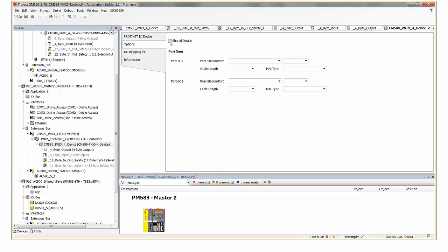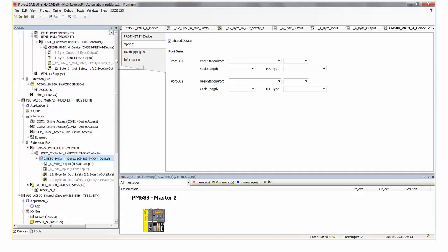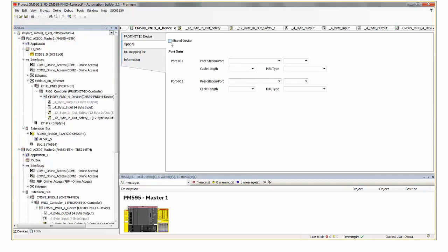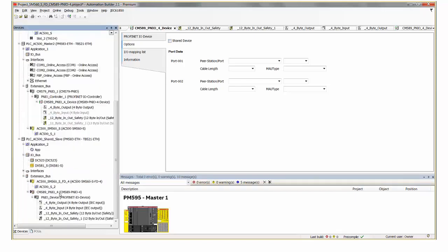All others have to select this. So what we'll do, we'll select it here. It means that on the other master system this parameter can be deselected, which is okay. It means that this device will have to put the primary configuration for shared device to the PROFINET IO device with shared device support, which is shown in this shared device project.